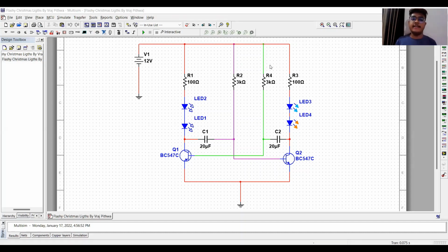Now, before the LED lights up, before the switch closes or the transistor is powered up, the voltage at the collector is the supply voltage and the voltage at the negative side of the capacitor is about 0.7 volt. Now, over the capacitor there is a voltage difference of the supply voltage minus 0.7 volt, that is VCC minus 0.7 volt, in the direction of the transistor collector. Now when the transistor is powered up, the voltage at the collector becomes 0 since it is connected to ground.